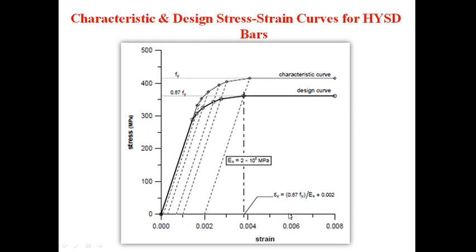So again it is stress versus strain for steel. For mild steel, we know that in strength of materials, when we test a mild steel bar, it is possible to locate the yield, whenever the steel gets yielded, that means the upper yield point or lower yield point. But for HYSD bars, that is high yield strength deformed bars like Fe415 or Fe500 or Fe550, it is somewhat difficult in the lab to locate the exact yield point, and therefore IS code says that this is the